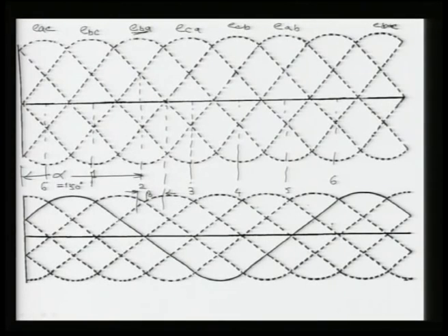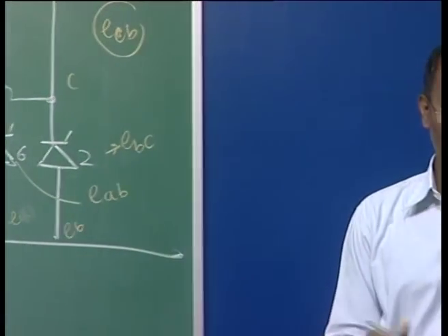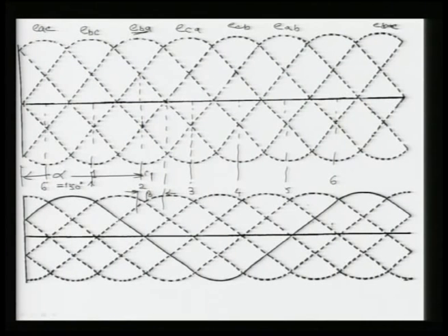I am saying this 1 is being fired. Let us start from here. Yeah, you can start from 2 because the EBC is given to you, the commutation voltage of valve 2. Here we are firing, at this value we are giving the pulse to 2. Now, before that your 6 and 1 were conducting, and 2 is given the pulse here. Now, your 6, 1, 2 are conducting, means just here for a few degrees 6, 1 and 2 are conducting, and this will be for 15 degree, means here it is 30 degree, so it will go up to here, the 15 degree, half of this.